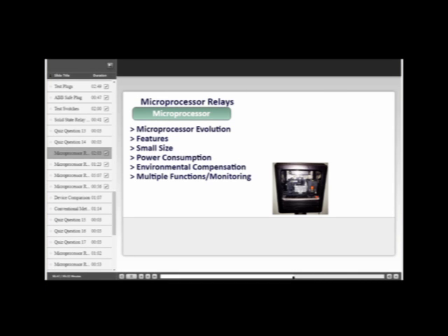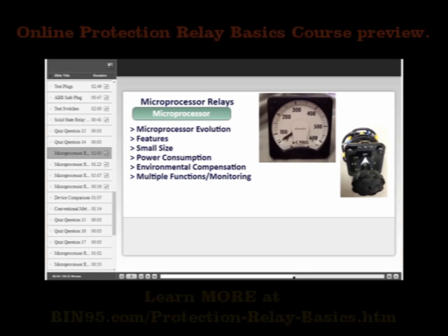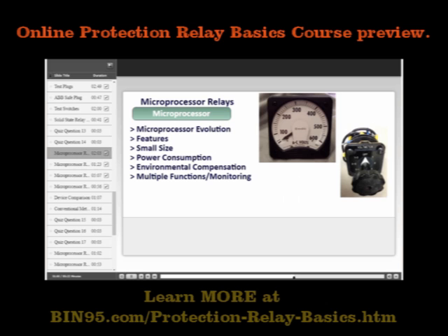Computer-based power monitoring equipment can be programmed to perform multiple functions in one package where several induction discs or solid-state relays would have needed to be utilized. In addition, the electronic unit can monitor and display many parameters, eliminating the need for metering and metering switches. This also saves on panel space.